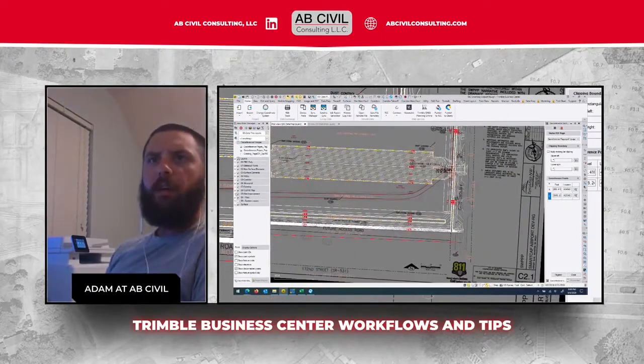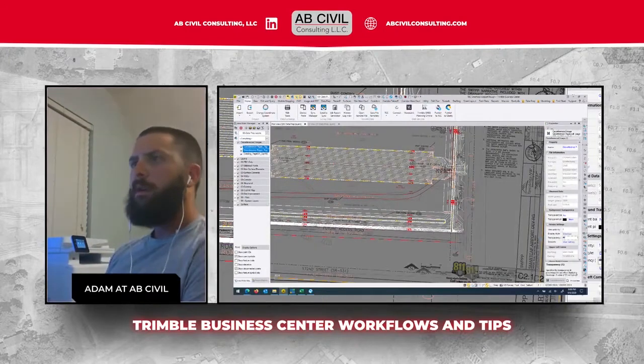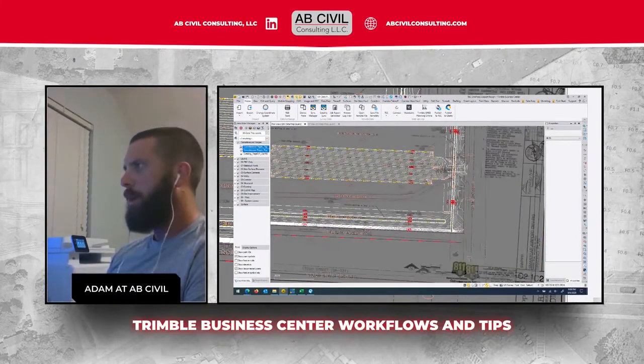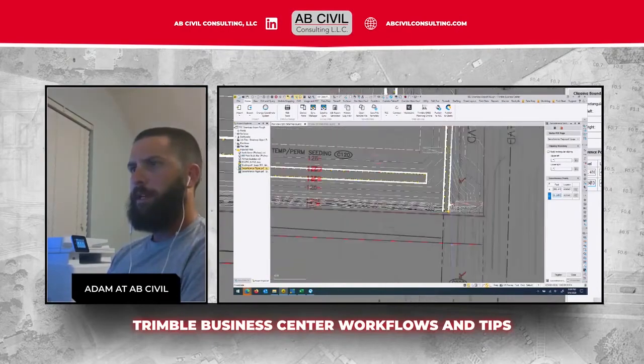Let me see if I can look at my other georeference PDF. So I'm going to change both of these to, I'm going to change their transparency to 40%. So if I turn both of them off, I can cycle between them and see where I might be off a little bit. So yeah, I can see a common line. So I'm going to pick this first one again. So pixel B, I'm going to change that one.